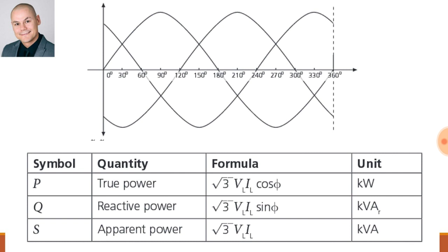This is just to illustrate what we mean by a three-phase motor. There are 3 sine waves, 120 degrees apart. Now, the big advantage of a three-phase motor is that it's self-starting because it has the difference in phases to allow it to start. If we look at this table below, we'll see and remind ourselves of the formulas required to do three-phase calculations.